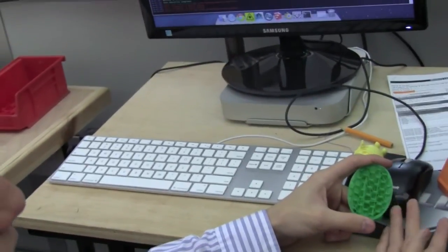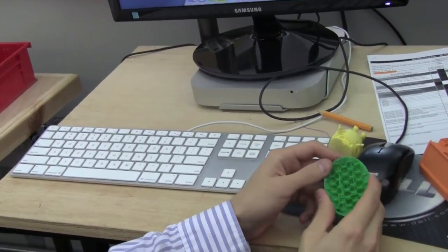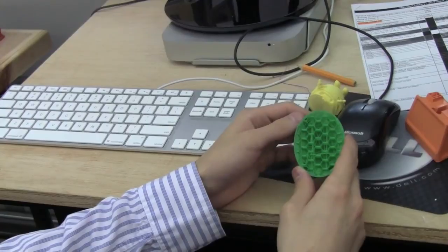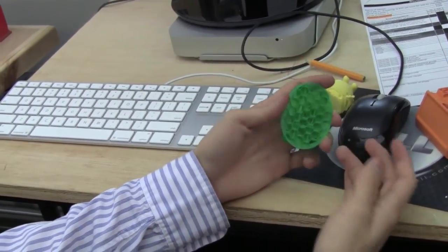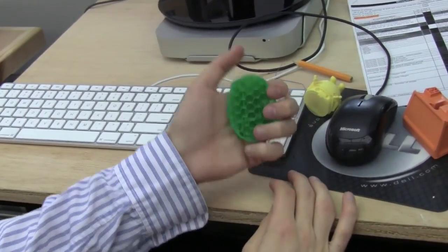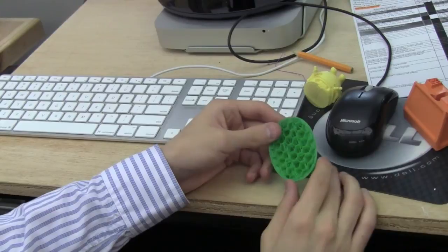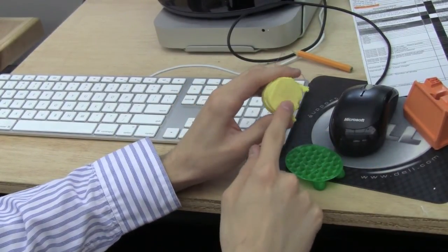So it's relatively hollow, it's pretty light, and it gives us some structural integrity because the honeycomb structure is pretty strong. This means you can save a lot of time and plastic, but it's also not as weak as if it were completely hollow, because then you could just puncture a hole in it, or squeeze it. Yeah, it's so thin. For example, if you were to do 100% infill, it would look like this, where the entire thing is completely filled with plastic.